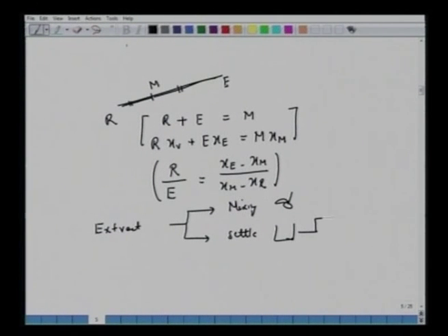And when we settle, there is a phase separation: extract phase and raffinate, which we sometimes also call residue. The extract will contain what we have extracted using a solvent, right? And raffinate is your feed, which will also contain some solvent, but C is smaller here. C is larger here. Some A will also go here. All right, this is A here, and some solvent B will also go here.